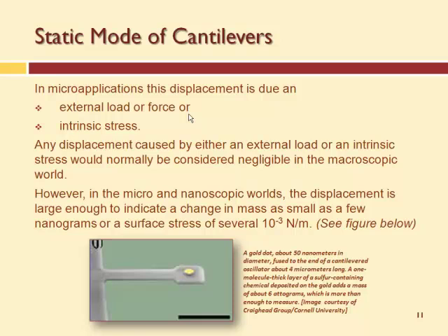There's intrinsic stress involved. You have two different materials in your cantilever. You put it in a different temperature environment, and one material will expand more than the other, so it'll bend. Depending on how it bends, you know what the temperature is. That would be an example of a static mode. Can you use piezoelectric for that too?